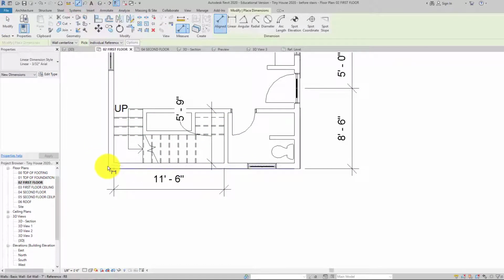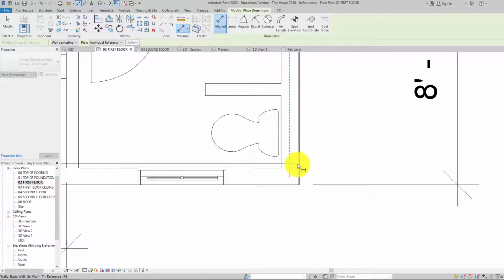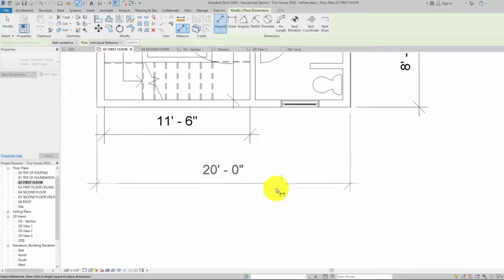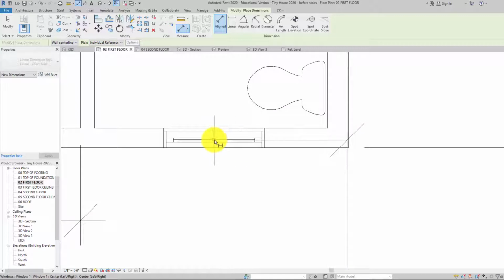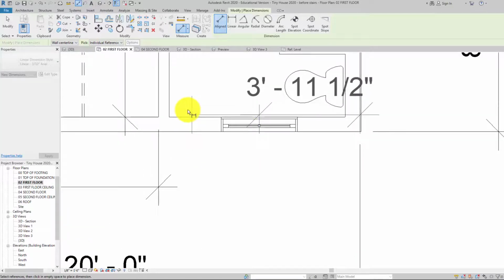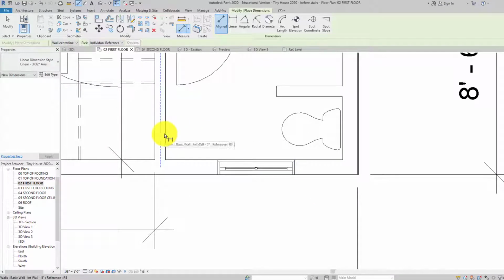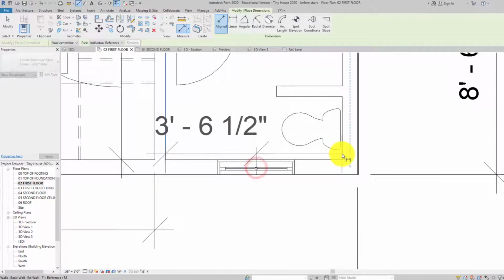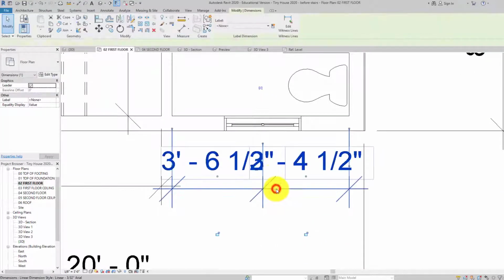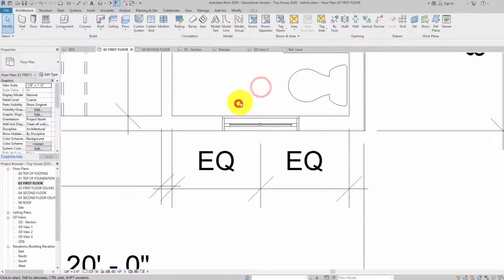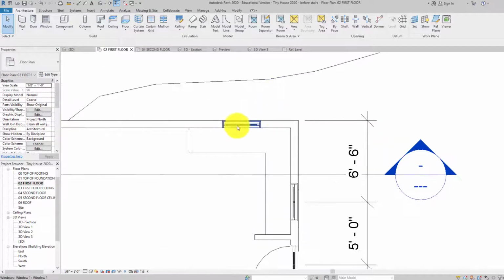So same thing. Having lots of dimensions here in a second. And again, I'm tabbing through. I'm always tabbing through. I don't want the siding, I want the actual wall. So this one, I don't want that. This one I'm going to grab the interior just like I did before, so I can put this right in the middle. You gotta hit escape, then click the 2 dimensions, and then click that equals button. Perfect.